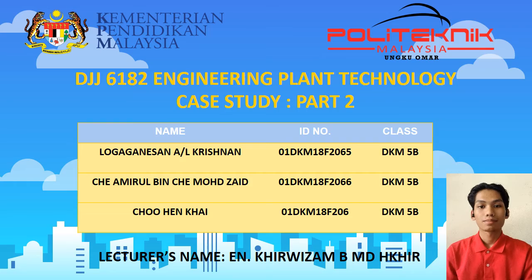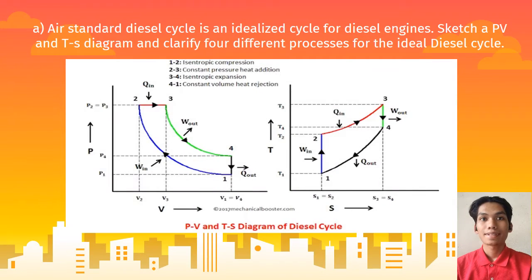The question from the case study is: a standard diesel cycle is an idealized cycle for diesel engine. Sketch a PV and TS diagram and clarify the different processes for the ideal diesel cycle. The picture below is the answer to our question. PV stands for pressure over volume diagram, and TS stands for temperature over entropy diagram.